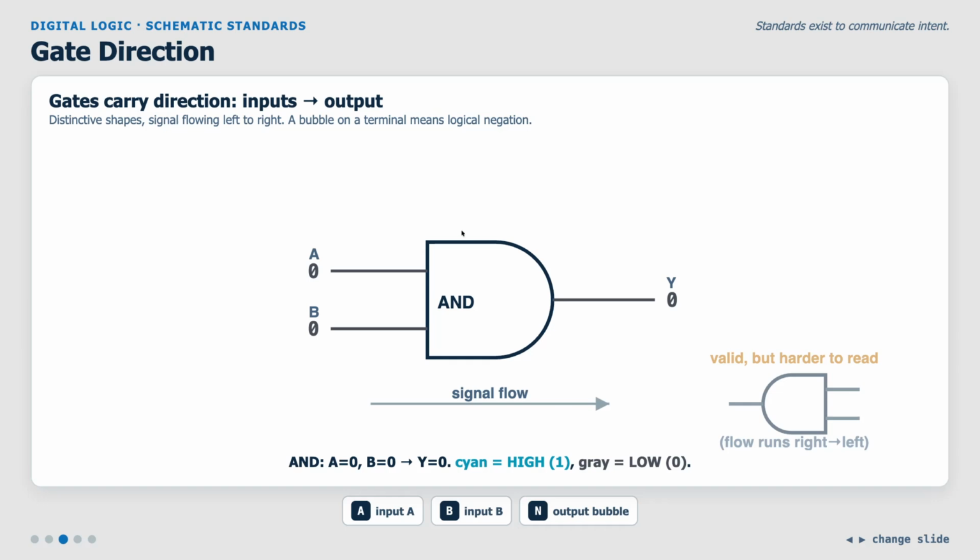Okay. The next thing I want to make it clear, I think it's obvious, but sometimes I need to state the obvious to make sure we're on the same page. Gates work in a direction. You have to have an input side. Okay, so I can press the button A here and you'll see, oh, this is sensitive to the input. And then B, when I press both A and B to be 1, it causes the output to change. So there's a direction to it, input to output, signal flow. That's important with digital circuits. Okay, there are some weird gates that don't have direction or are bidirectional, but we'll get to those later at the end of the course.